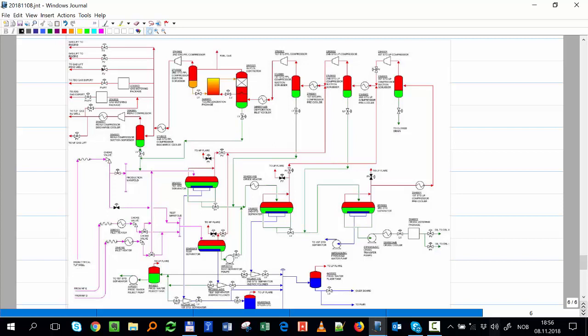It's a type of platform we have offshore, in which, let's paint the sea. Then we have our platform, we have our separator on top of that platform. But the way that platform is held, let me paint the soil, something like that. I use tension cables to bring it down, and it's positively buoyant. If these cables, for some reason, are broken, the platform will go up.